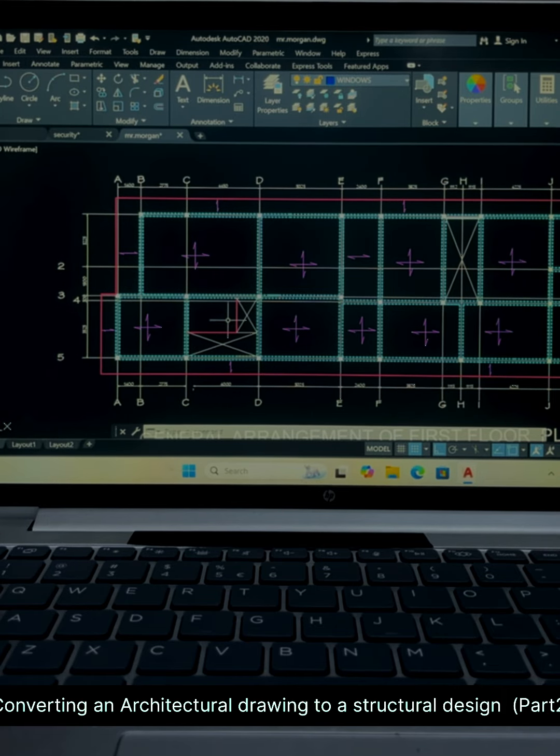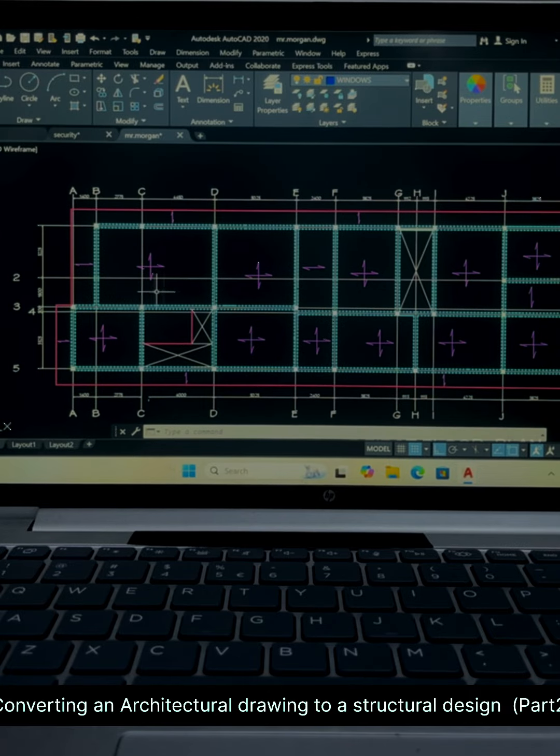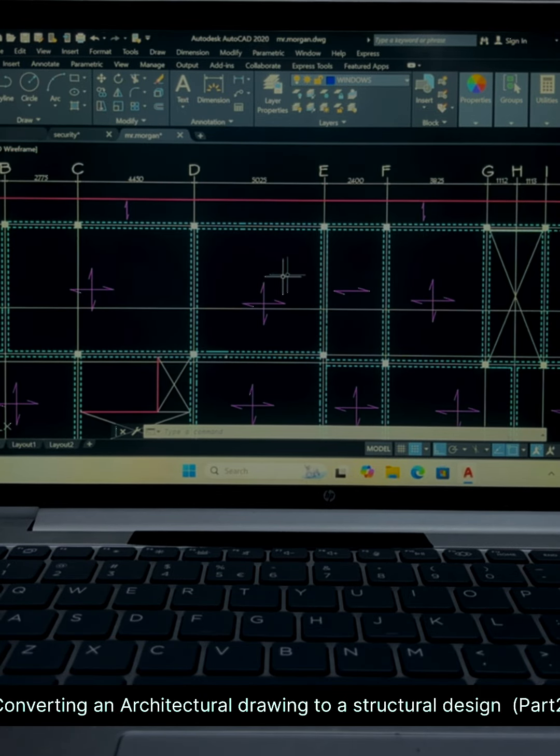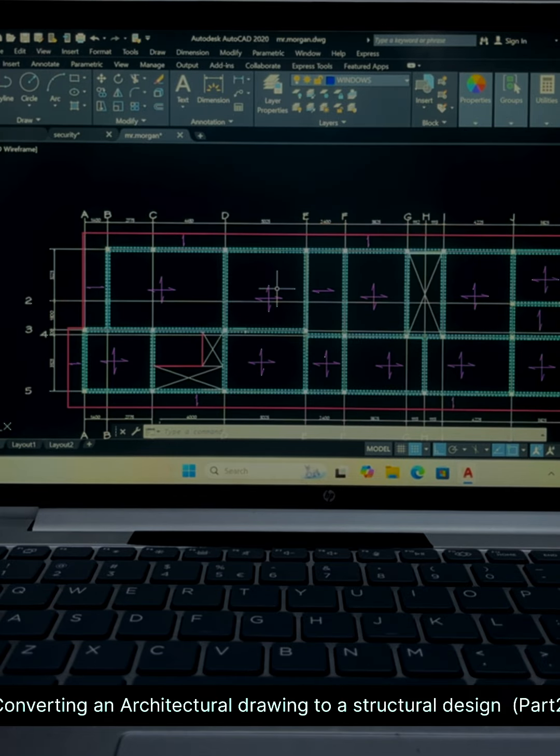So like we can see here, basic information: by inspection, I can see that this panel here is designed as two-way. This one here as two-way. This one as a one-way slab. And all the cantilevers should be designed as one-way slabs. So once you get your general arrangement done, you can now go ahead and start your analysis and design.